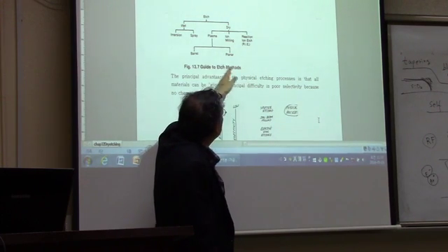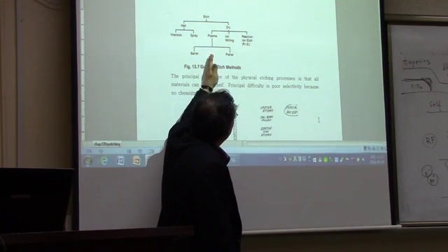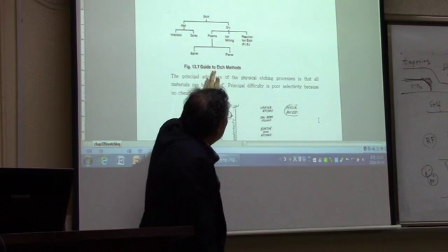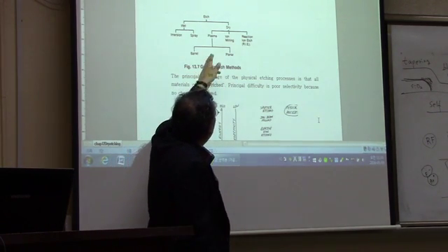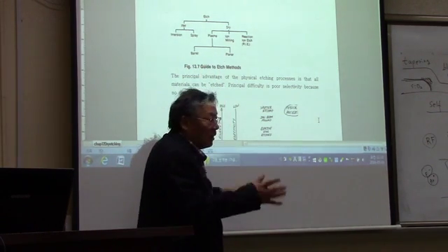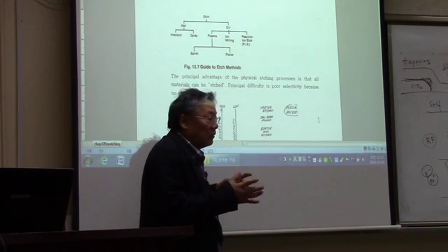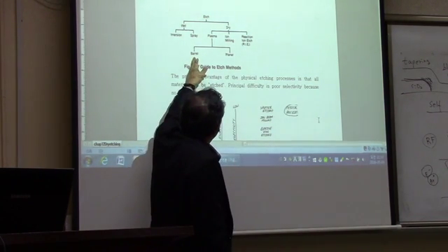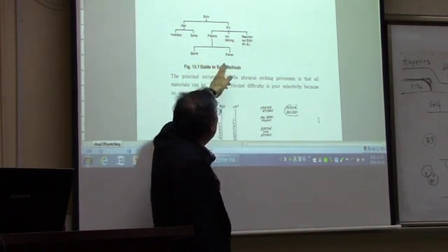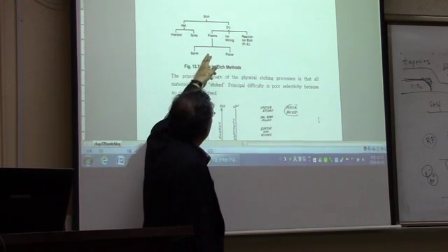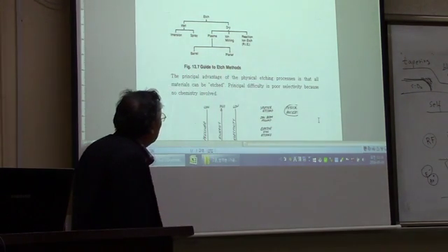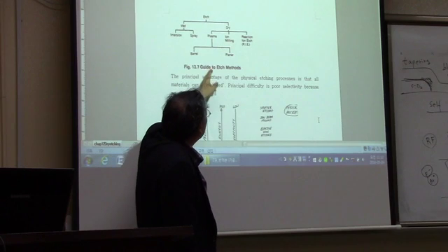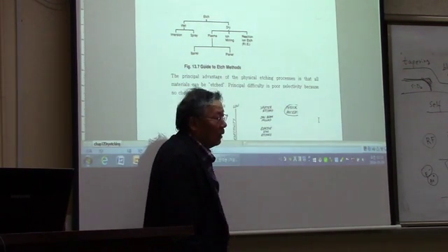And in dry etching, we use a barrel type. That is a plasma, just a chemical process. Neutral atoms are involved, and typically we have a barrel type and a planar type for this plasma etching. The barrel type is 10 torr, the planar type 1 torr.